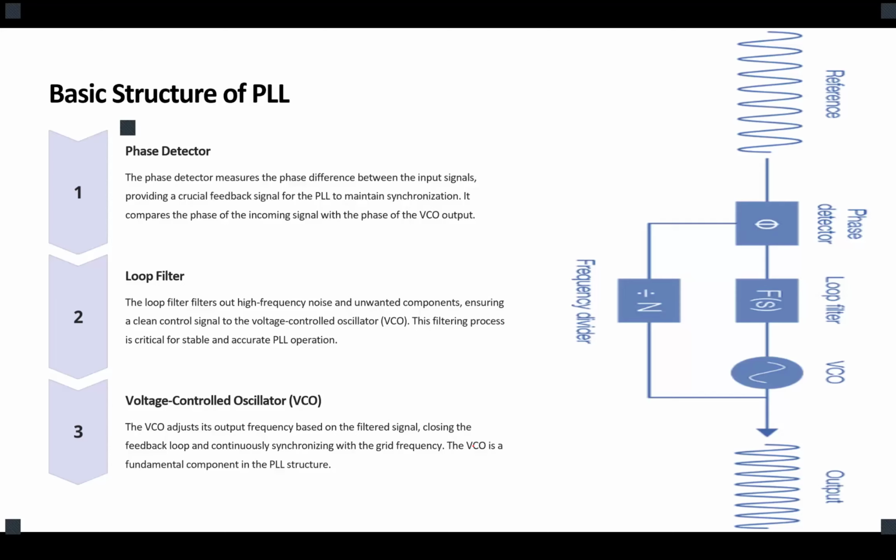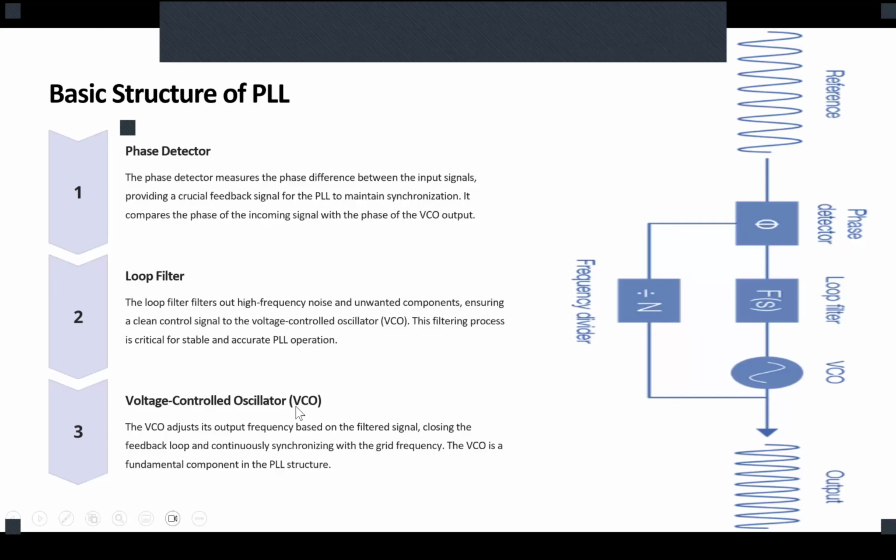Are we good? So now what creates that sinusoidal voltage is the VCO in the PLL. So this output is the reference signal in your PWM. Is that clear? Any question about that? Which one, the sine or the triangle, is what goes to it? The sine, the reference one. This VCO creates a sinusoidal voltage, which you can use for your reference because it has the proper frequency.